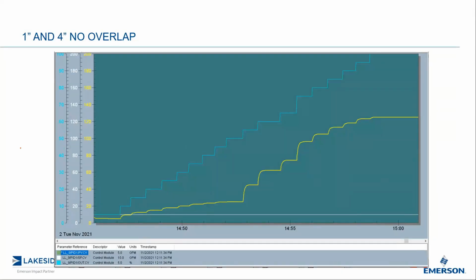So this is what I did earlier on. These are consistently 5% output changes. And you can see here, I'm opening the small valve, and the valve is dying off right around this point. And then now I start to actuate the big valve. And obviously it's a very, very nonlinear approach. So this is probably the extreme case. And obviously do not do this at home, kids, okay? Do not do this at home.